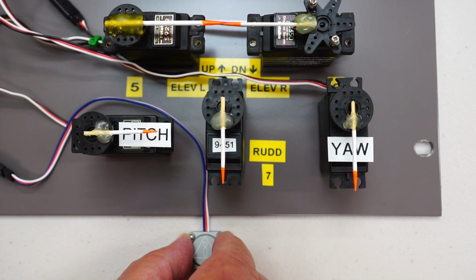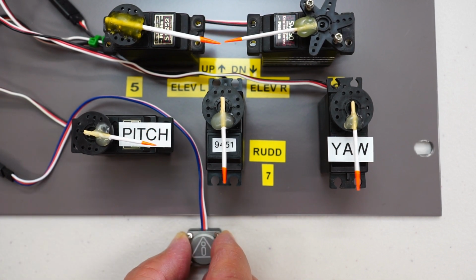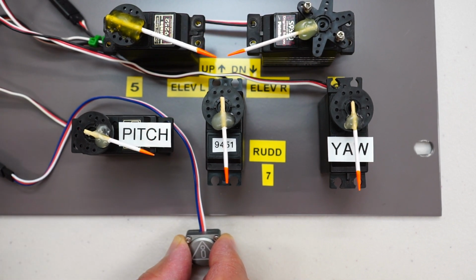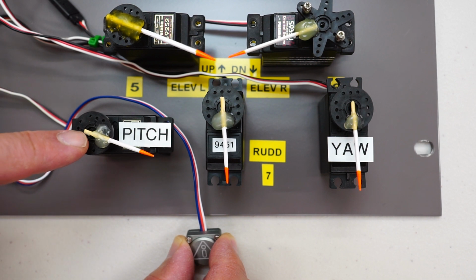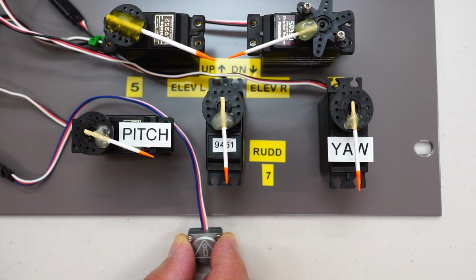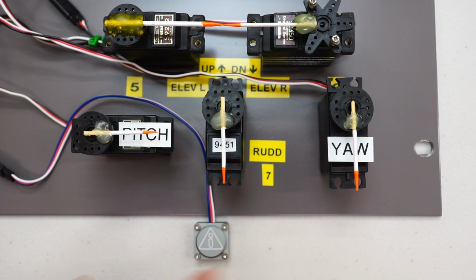And same goes for the pitch elevator control. If I pitch the nose up, so I'm going to move the front of the sensor upwards, just like that, we basically have down elevator. So if the nose of the aircraft goes up, we have down elevator, as well as the pitch control on the vectored thrust moves down to try and point the tail in an upwards direction to counteract the nose up attitude. So that's all working correctly.